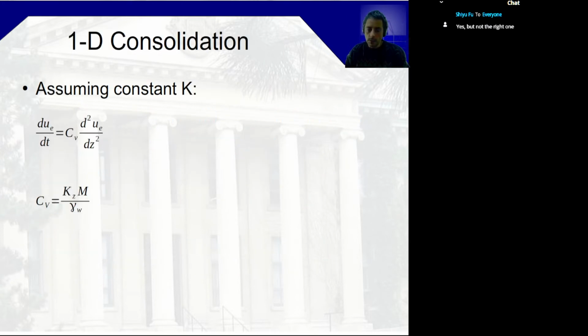This is how we are going to calculate the dissipation of pore pressure. In the first place you assume that all of the stress goes to the pore water pressure. Yes, and that tells us the maximum pore pressure, right? But there will be a change over time because we need to get to the steady state condition.